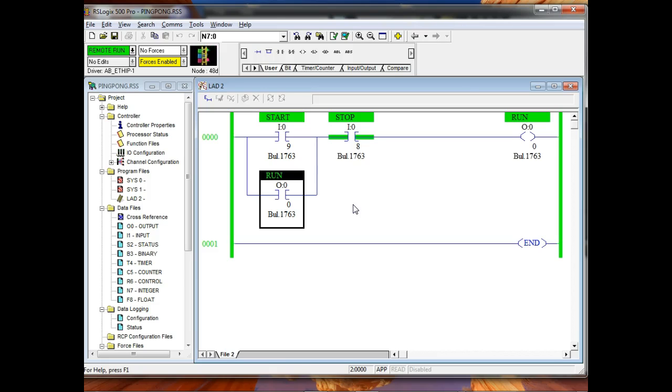On these guys, you can simulate a normally closed contact. You just simulate a normally closed contact, like just leave the switch wide on. On the 1000s, all the push buttons on the trainer are normally open. But what they have on the right hand side is a selector switch that you can use to simulate what? Normally closed. Okay.